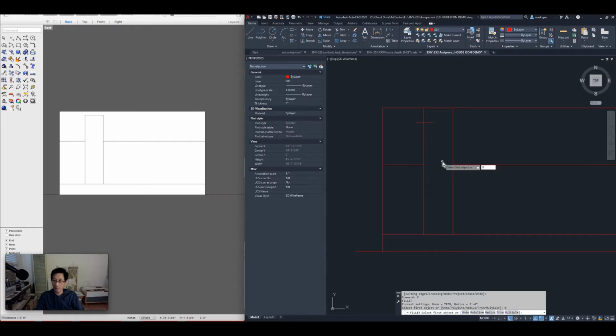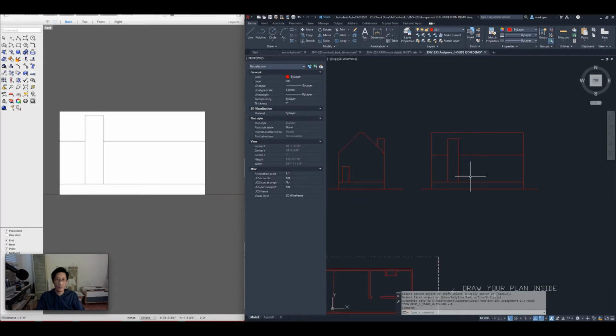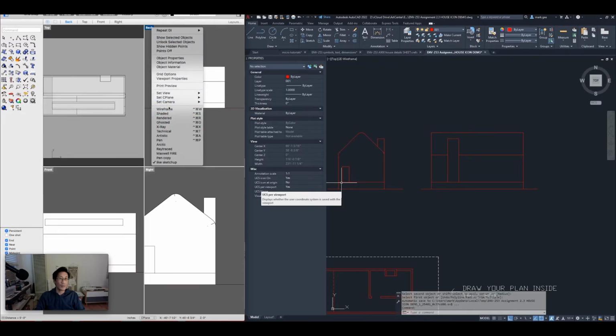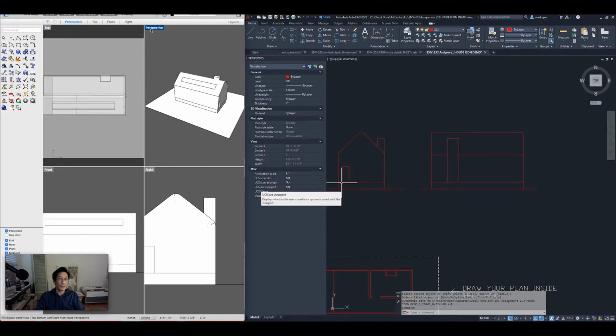Whoops, I need to type R first to tell it we want to specify a radius, 0. So 0. And again, we can do multiples. So I'll type M because I want to use this more than one time. Multiple, M. Click one line, click another one, click another one, and another one, and there. And zoom out. There's that elevation. So that's our second elevation. Let's go back to our perspective view.